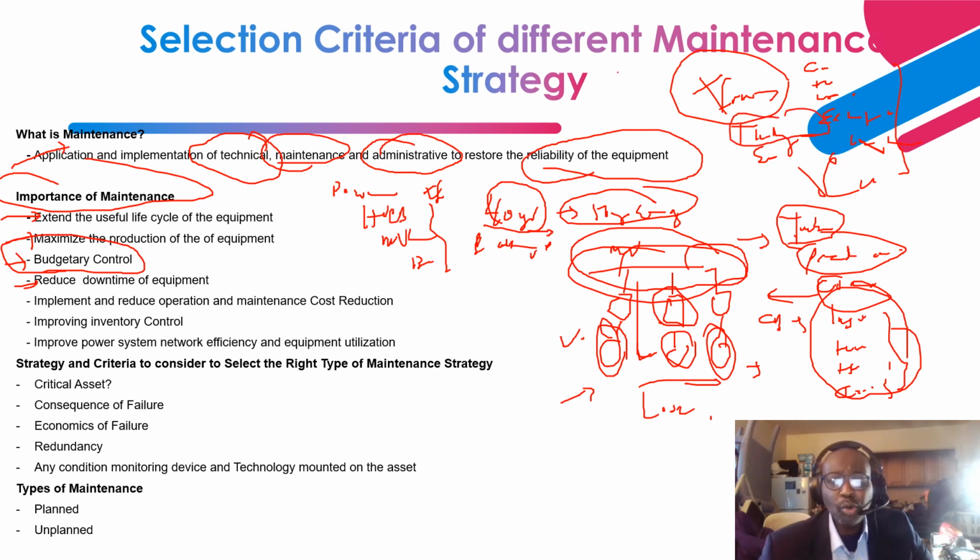In addition to collecting oil samples for DGA and oil quality analysis. For oil quality analysis, you can make mention of moisture, breakdown voltage, acidity, neutralization number, interfacial tension (IFT), etc., just to name a few of them.